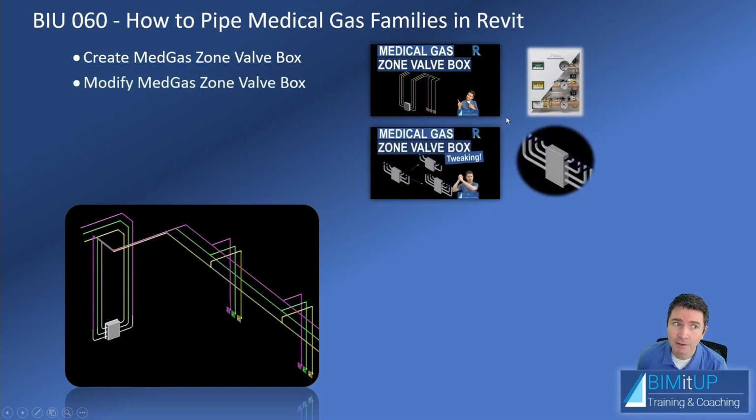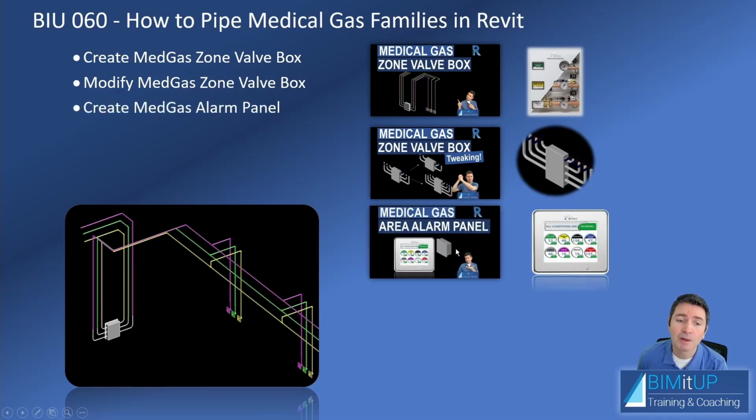Then on the next video I showed you how to modify that medical gas zone valve box so that you could obtain either a 2 gas valve box or a 4 gas valve box. Then on the next video, I showed you how to create a medical gas alarm panel, which is the alarm panel that's going to be monitoring that particular medical gas zone valve box.